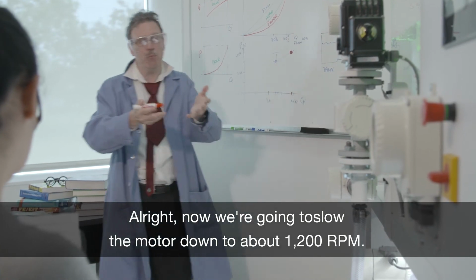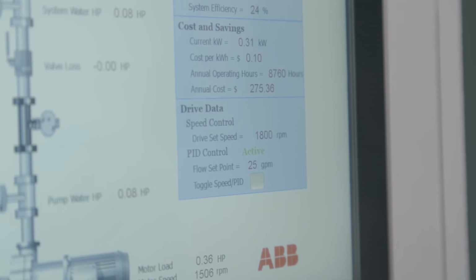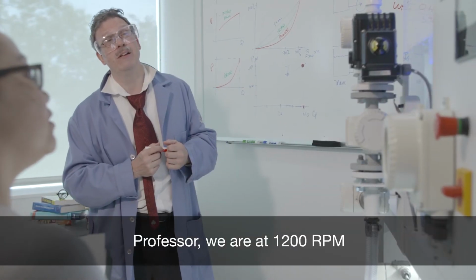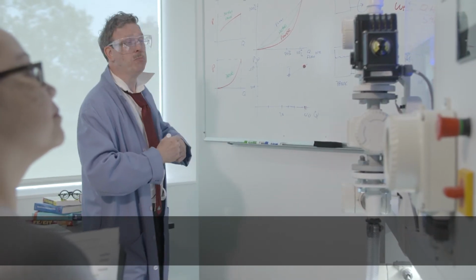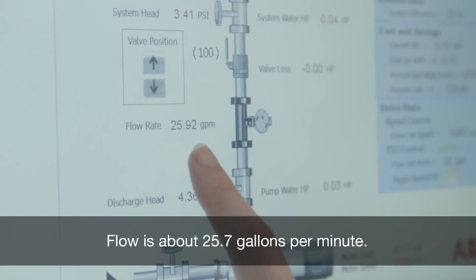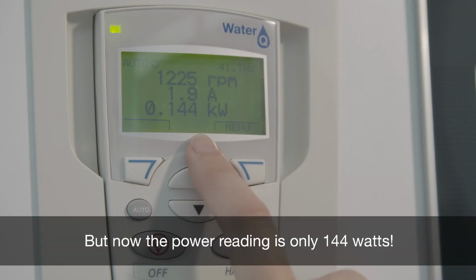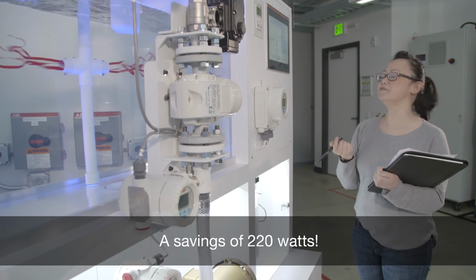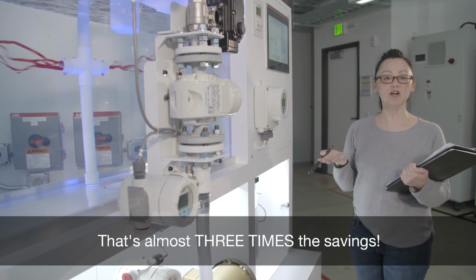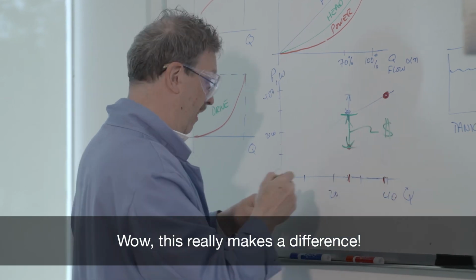Now we're going to have to slow the motor down to about, say, 1200 RPM. Professor, we are at 1200 RPM. Perfect. Now what do we have for flow and power? Flow is about 25.7 gallons per minute. Okay. But now the power reading is only 144 watts. A savings of 220 watts. That's almost 3 times the savings. Wow, this really makes a difference.